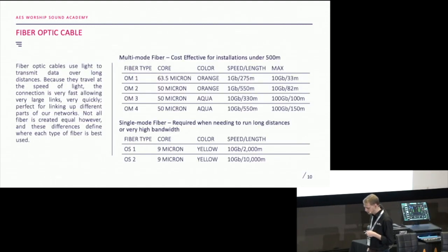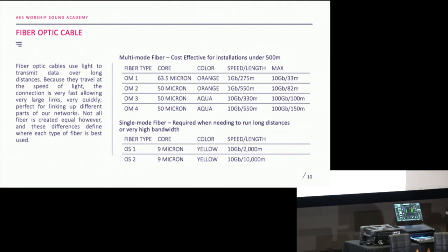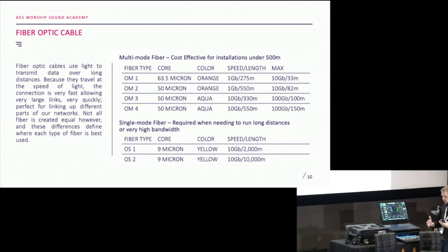Fiber optic cabling, right? So we say I need to go more than 300 feet. Well, then we've got to convert that electrical signal that's run on those copper pins to light, because light can run a lot further than our copper can, with much less loss. So again, I'm trying to arm you with this information as you're starting to think through, I want to start to implement some of this stuff. So what are the pitfalls? What are the things I need to watch out for when I'm thinking about, okay, I want to do fiber optics. I know that I need to go more than 300 feet.